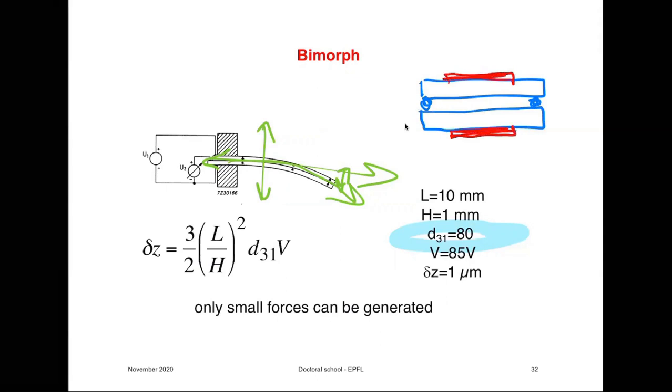And then when you apply a voltage on these piezoelectric discs, because they will change their size and the metal tends to oppose it, the whole structure will bend either like this or like this, and that will cause air to be either expelled or inhaled inside the structure, and with that you can cool.